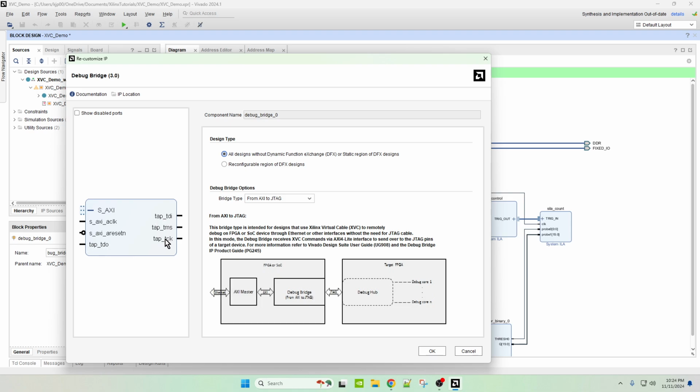And so you can route these out and then attach it to a target FPGA and then debug and use this kind of as a smart link. And it's pretty neat because you can instantiate as many of these as you want. So you could have one that's instantiated inside the firmware itself, and then you could have several external JTAG ports, in the case of like a test fixture or for automatic testing or things like that. This is super awesome for making mainly just test fixtures, but it's still pretty cool.